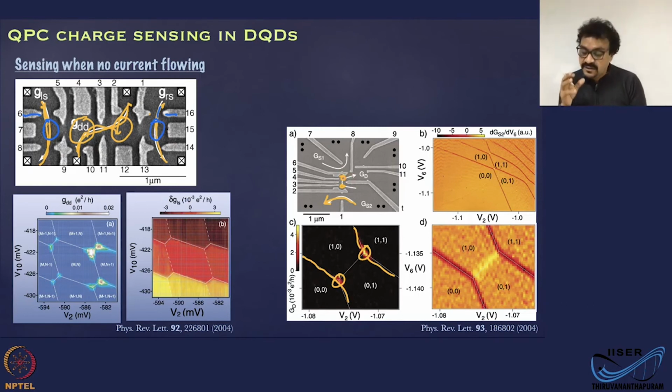And it is telling you a lot more information than the direct current measurement to the system. So the charge sensor in this way is a lot more superior to the current measuring technique whenever it comes to nanoscale devices where the current levels are really, really low.